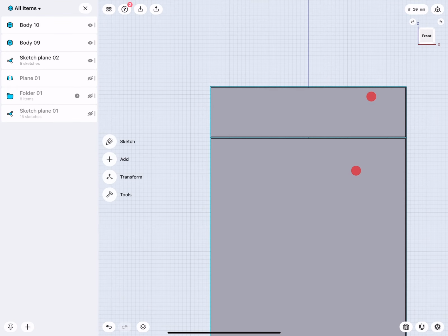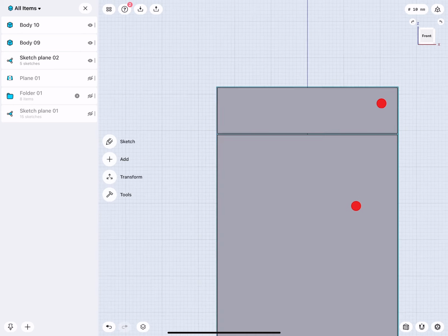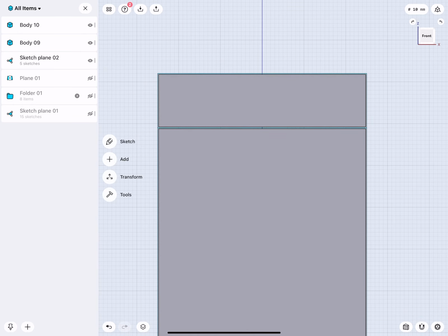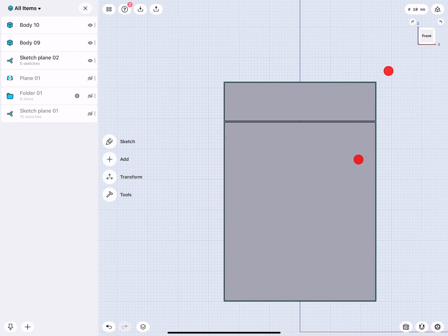So this gap is actually also needed when, for example, we have to level out a drawer, because then this front face will rotate a little bit. When they're perfectly flush onto each other, that's not very good. Plus, wood is a living material. It might expand, might shrink based on the air moisture.